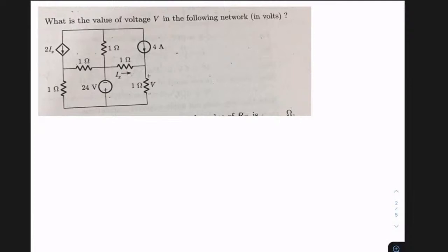The technique in this case is, let us say this is your node A and this is your node B. The network from the AB terminal can be replaced by the Thevenin model, which is VTH in series with RTH, at the same AB terminal.